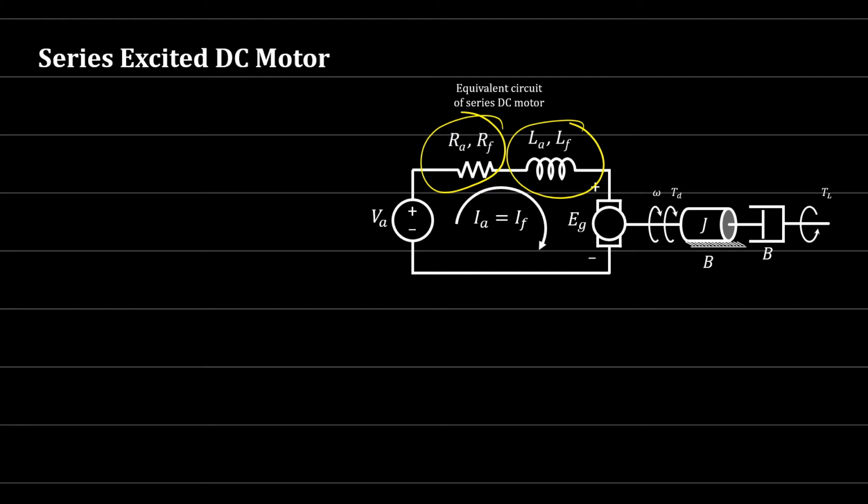The field circuit was also designed in a way to tolerate the armature current, okay, and the steady state average can be obtained, as we'll see now. But the key point is here, the armature current and the field current are the same current in reality. So here we have IF and IA, the same value. The field circuit is designed also to apply a magnetic field in the motor.